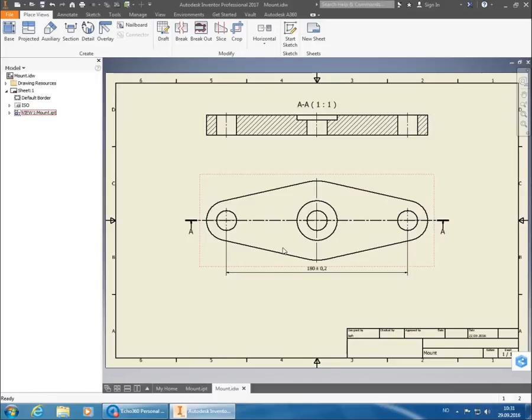In order to make this a bit easier to read when I'm going to put notes on the holes, I'm going to move the AA mark for the section. I'm going to move it to below the section instead. It is usually given below the section, but I see that Inventor often places it on top of the section.